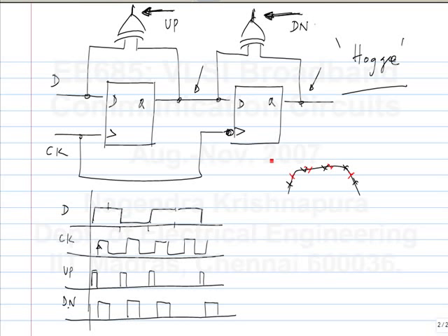If you have an analog type of technique, then you can't uniquely define it, right? So if you have clock at twice the data rate, you will get something similar. In fact, many circuits have this problem of locking to the harmonics. If you send a clock at exactly twice the rate of the data, then you will get more or less similar output, and then it may lock. But usually that doesn't happen because when you are already transmitting at a high frequency, you don't clock it at such a high frequency. Also, when you have a VCO, it is not likely that if you design it for 5, it will go to 10 and then lock to the harmonic.